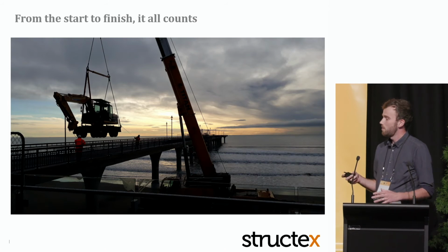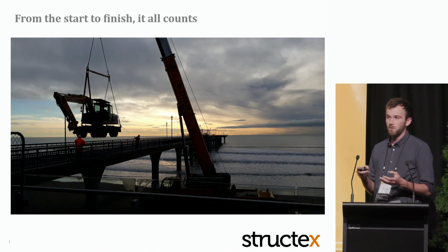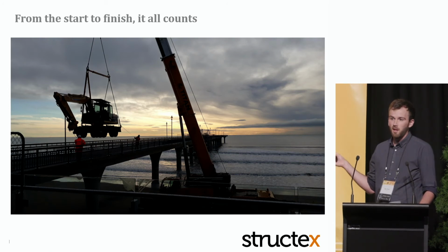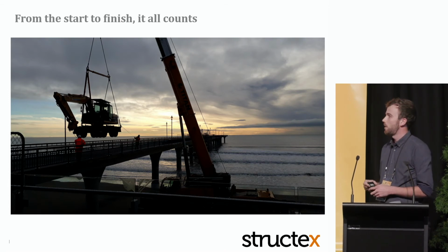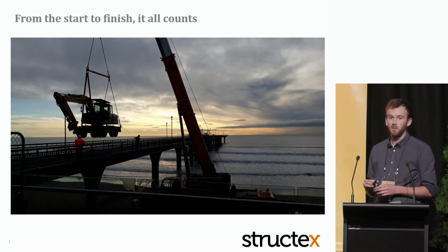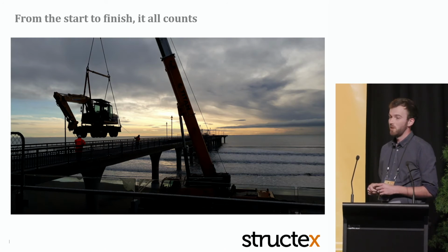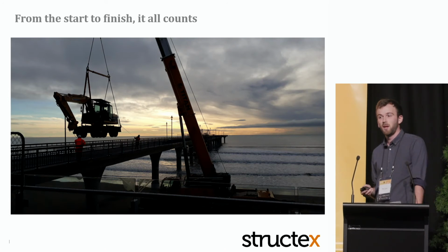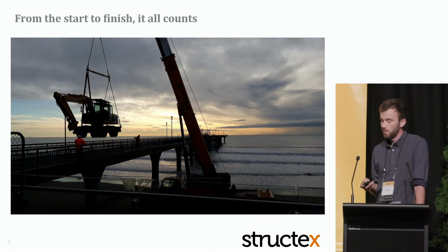Another thing is thinking about, when you're designing your structures, long-term remediation strategies and how remediation will be carried out. So in this case, the pier itself was designed for full HN loading, but the access ramp could only basically take a ute. So it creates quite a challenge when you're trying to get a rather large wheeled excavator up there. So we had to have a crane pad and the knock-on costs and timing associated with that. So really thinking about start to finish, what's your structure going to see?